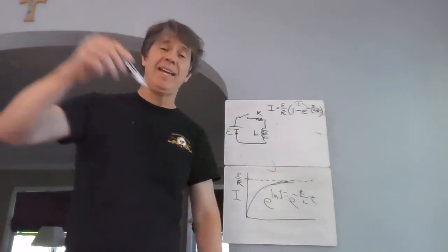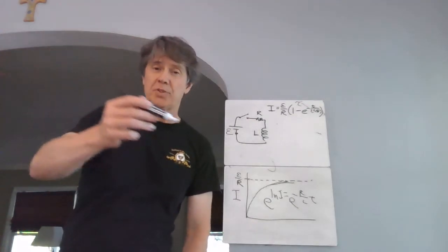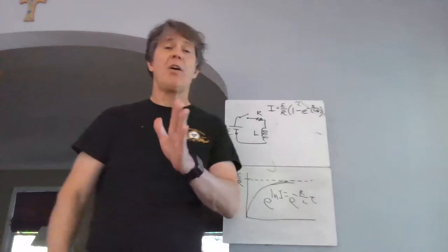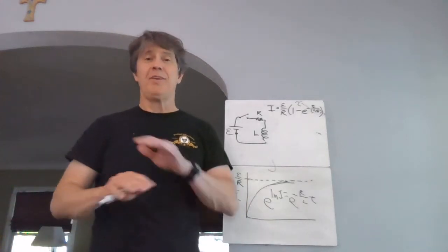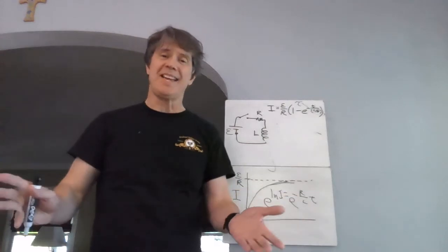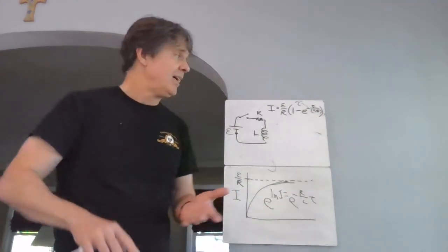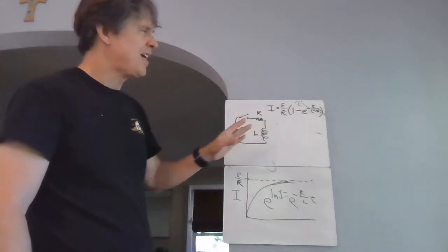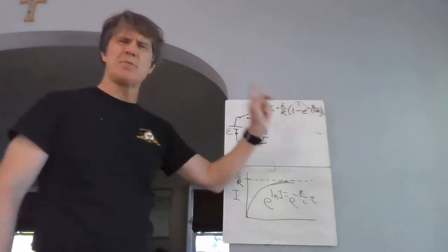Like if you're decaying, remember a discharging capacitor? A capacitor will discharge, and there the time constant is RC. We talked about that before. If you have a big resistance, that's going to slow things down. If you have a huge parking lot, lots of capacitance, then you're also going to slow down the time it takes to fill it. Look at the role this plays here. Longer times happen if you have apparently bigger inductors and smaller resistors.